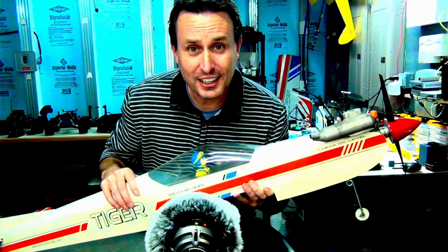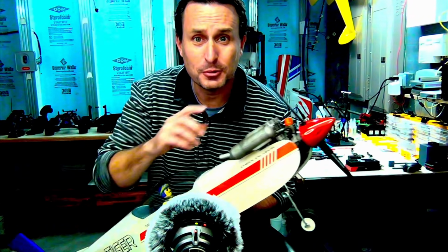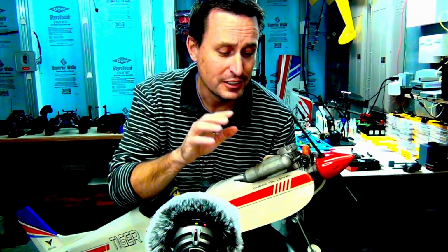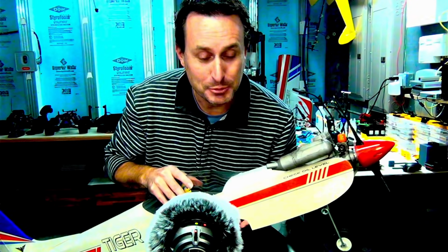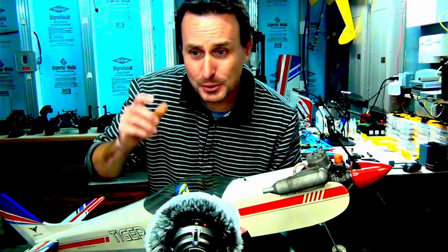And if you have something like this with an engine and you're looking to put a flight controller on it, BetaFlight has a lot to offer for something like this as well, where this is going to put off a lot of vibration. By and large, BetaFlight has the best filtering, with the dynamic notch that you would use on something like this, because this puts off a lot of vibration. So that would be the two use cases for BetaFlight, but enough gabbing.